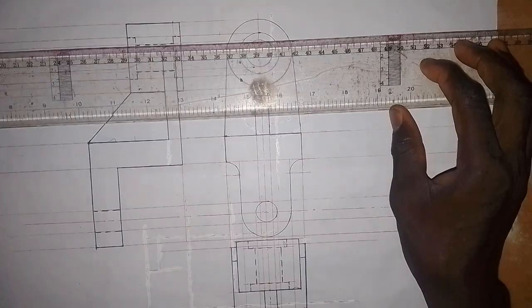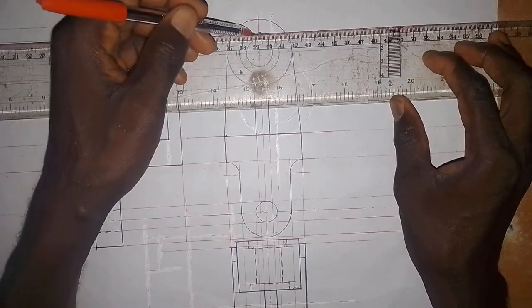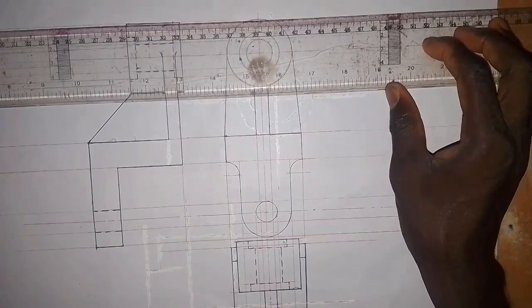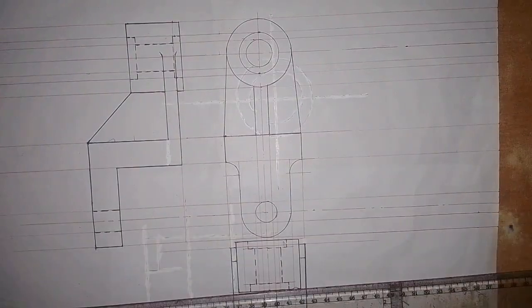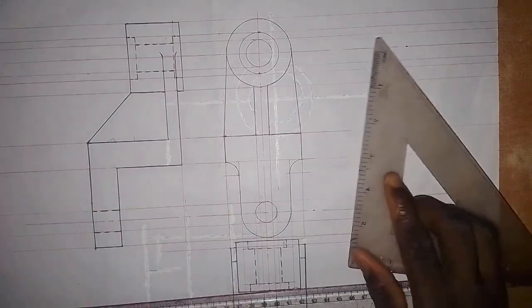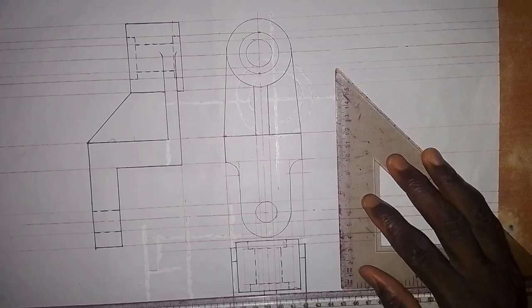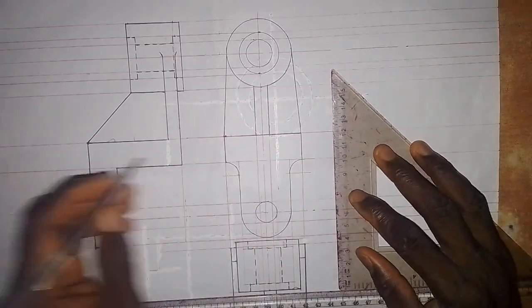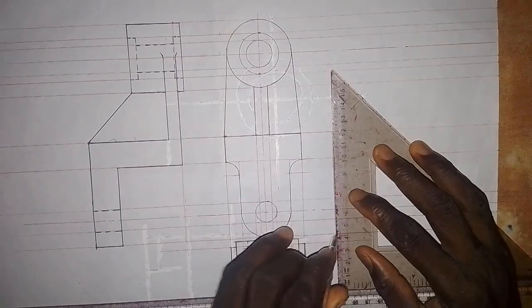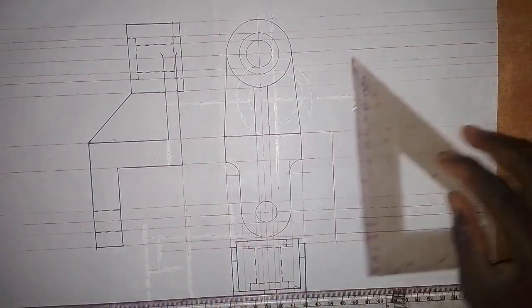Then coming up here, I'm going to extend the horizontal line to the right side, and also I will extend this to the right side, and at this point I will also extend the horizontal line here to the right side. Okay, so we have this now. What we are going to do now is come here. This line, I want to draw it from this point down. I'm going to make it a thick line at once from this point down. So we have it like this, drawn as a thick line as we have it here in the right end elevation.